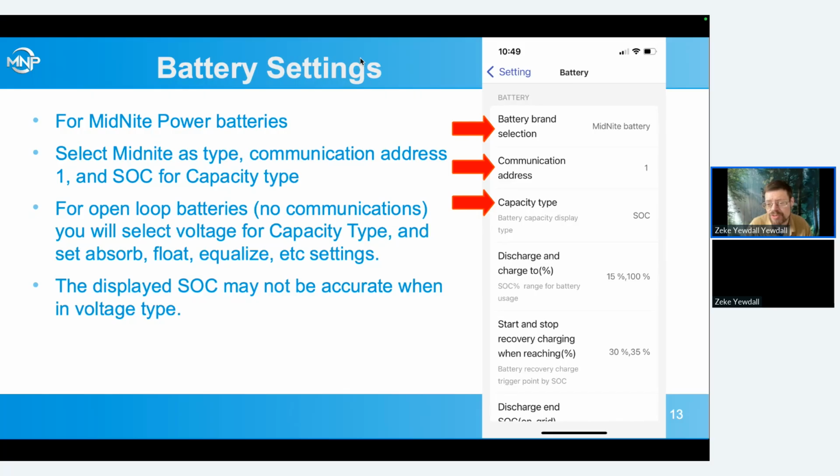So if you hooked up a generator that was a little low in frequency, it could actually reset the inverter to be 50 hertz. And then we would actually have to go in from the factory command line control and reset it to be 60 hertz. So just something to be aware of if you are using a generator on that AC in: if its frequency is too far out of whack, it can cause additional problems.